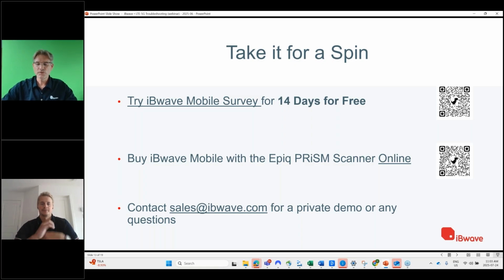Interference. Yes, you will see the interference with the spectrum analyzer, and this is the great solution here. It has a spectrum analyzer integrated, so you can take any frequency, set it to a specific wanted frequency, and you can see if there's any signal, any spike or something in your frequency band which interferes here. From the signaling itself, it should not interfere, but that's why you have a spectrum analyzer with you as a troubleshooting tool.